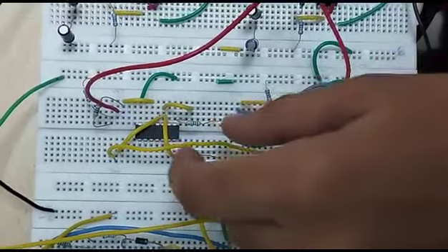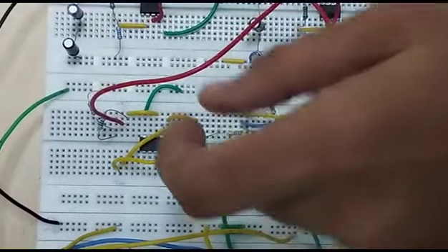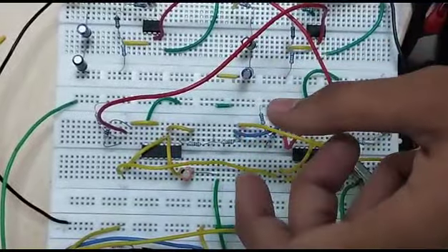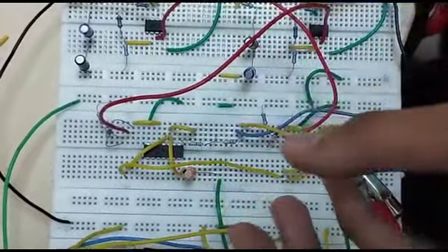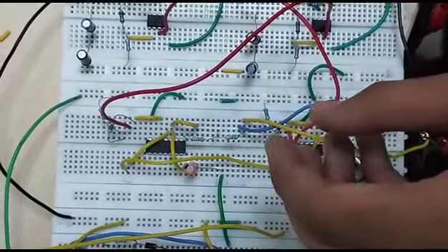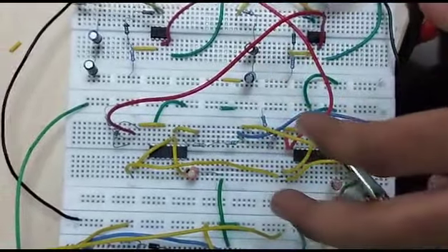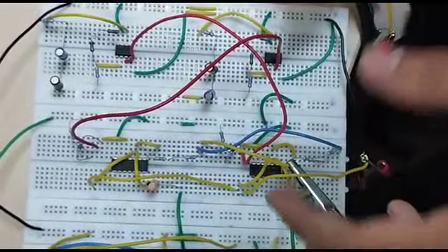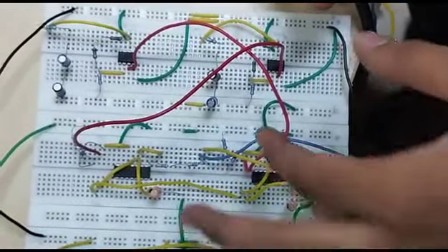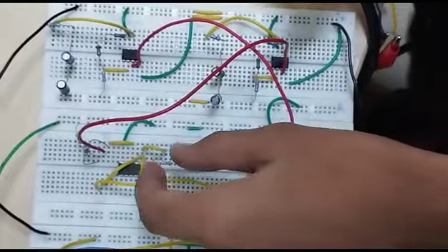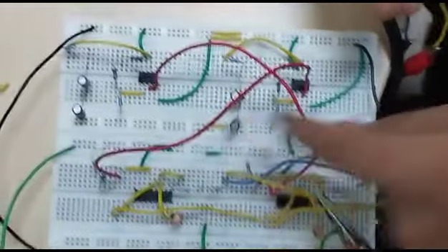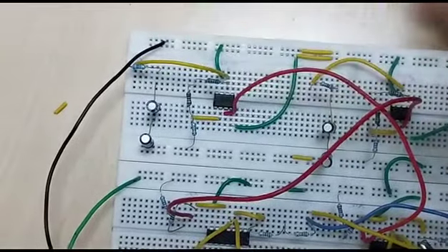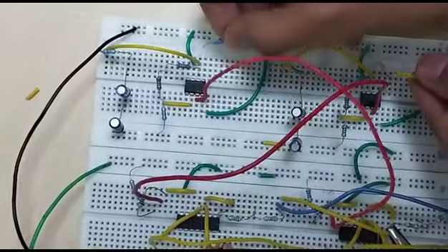Since the output of the MOSFET switch is really low, observing it with an oscilloscope is a tough job, because it is nearly around 50 to 100 millivolts, which is almost equivalent to the noise amplitude. So noise is equally dominating the output signal. So we are just amplifying it using a non-inverting amplifier here, and then passing it to low pass filters to observe the output more clearly. Now